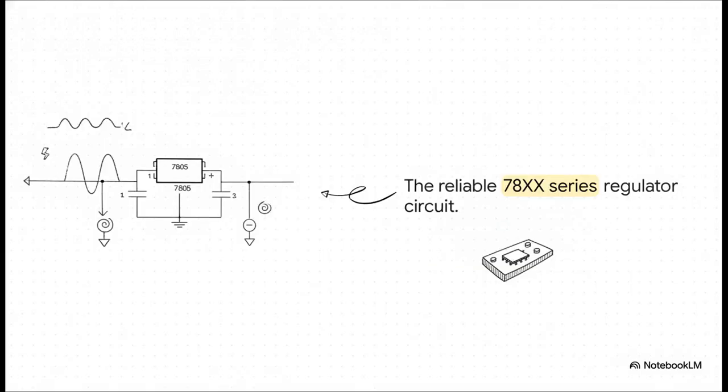When you build it into a finished circuit, just look how beautifully simple this is compared to the massive bridges and filters we started with. This little 3-terminal chip takes our filtered, still slightly bumpy input on pin 1, dumps any excess noise directly to ground on pin 2, and uses its internal microscopic transistors to deliver a perfectly safe, perfectly stable, and completely flat voltage right out of pin 3. Add 2 tiny capacitors to prevent oscillation, and boom, you have a flawless power supply.